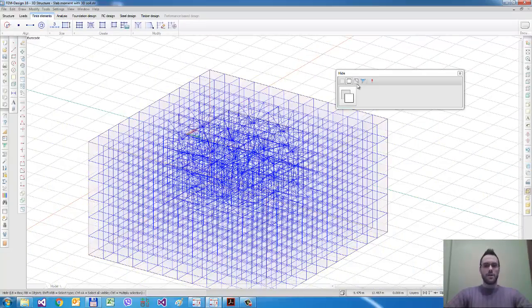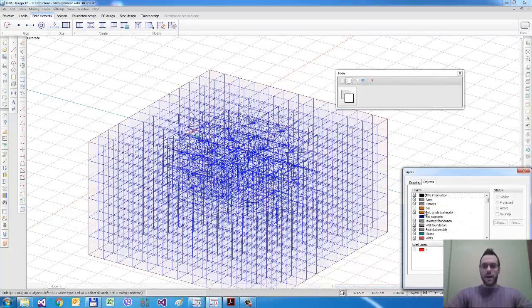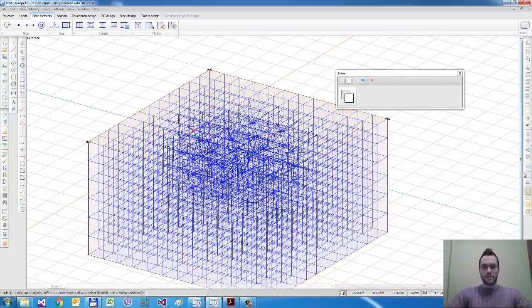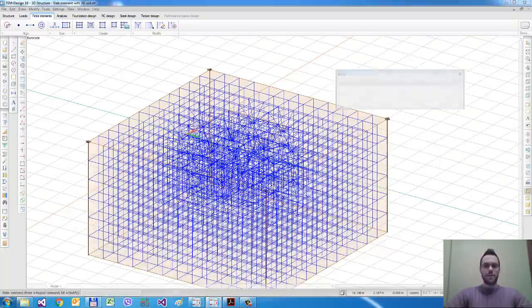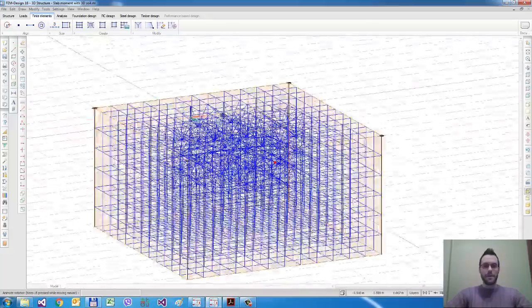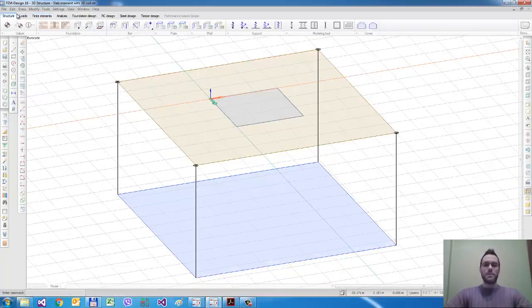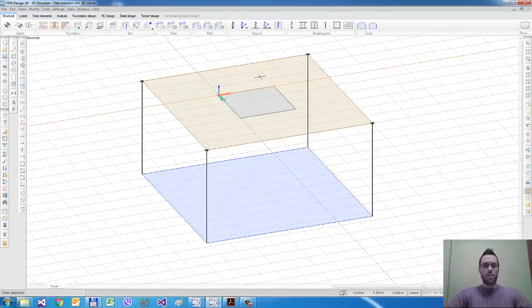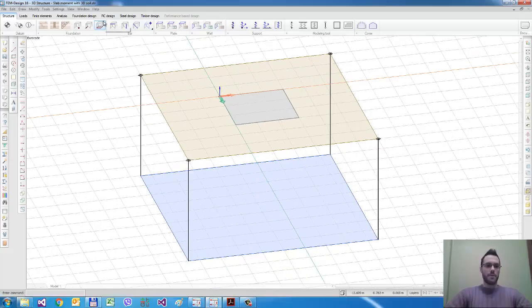So this was not a nonlinear soil calculation, but it was a three-dimensional soil calculation. It means that these differences come not just from different material properties, they come from the 3D soil behavior. So if we use the bedding modulus in the most simple way, we can get quite different results compared to when we use the more accurate modeling method with three-dimensional solid elements.